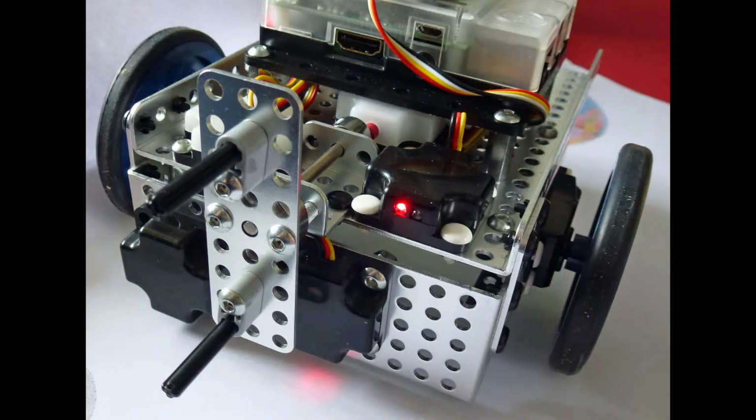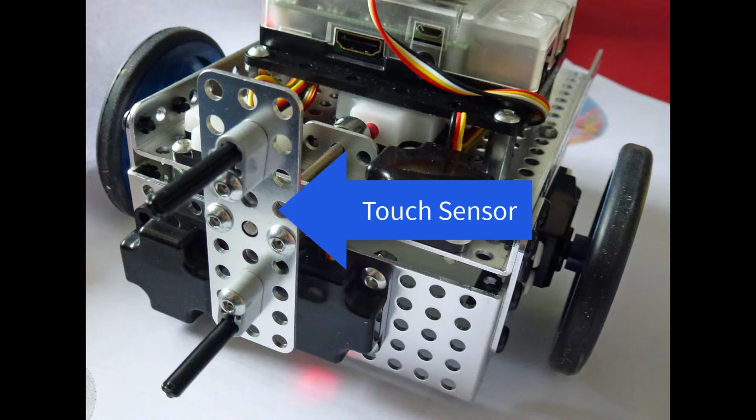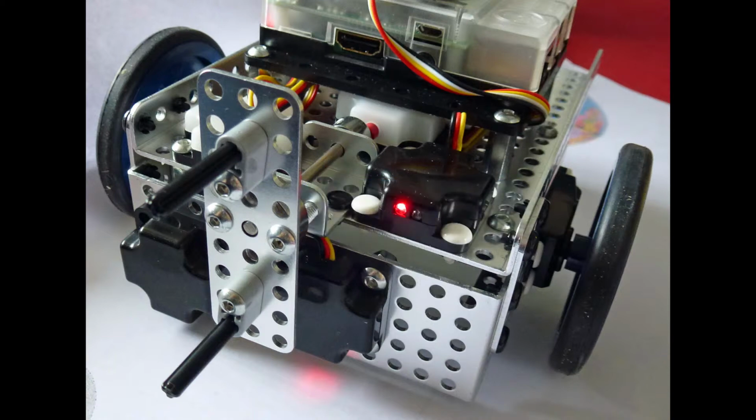We ran into problems. The wall following worked okay, but the optical distance sensor, which was sensing the wall, was spread out sufficiently in its detection ability that it started to detect the end wall before the touch sensor had touched the end wall. This meant the robot started to turn and it jammed in the corner. We tried lots of ways of adjusting the optical distance sensor, but nothing really was satisfactory.